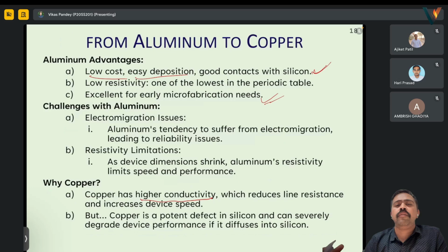Substrate temperature is used in combination, and that's why in some cases someone was asking a question some weeks ago about what temperature or wafer heating we use. In the case of sputtering, we use wafer heating, as we do in thermal evaporation also. To counter this energy problem, some heating is used, but we cannot go heating everything, only some heating according to our need. If we are not able to form the film and a lot of scattering is happening, temperature helps in countering the problem. Fine.